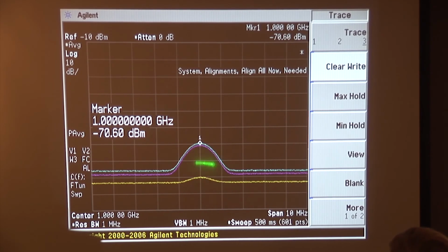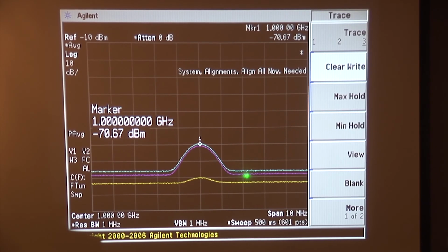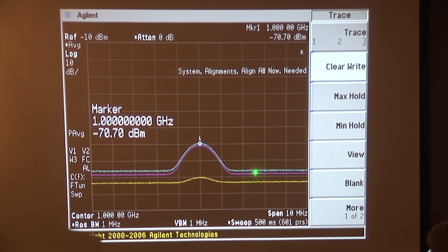Okay, so now what happened was, by putting in that next 4 dB of attenuation, just as I said, we didn't really buy ourselves more than maybe another dB and a half of dynamic range. The purple is maybe a dB and a half below the cyan now, but the signal to noise ratio went back down to about 16, maybe 17 dB. So that last 4 dB of attenuation is debatable. Maybe yes, maybe no. That's right in the gray zone. You could go either way. You wouldn't be marked wrong either way.